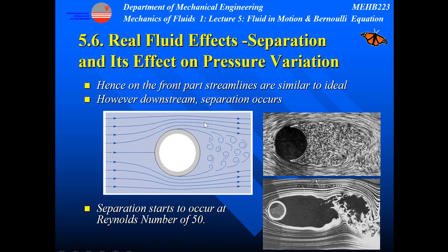You can only see some disturbance here. This disturbance is called wake, W-A-K-E. Separation starts to occur at Reynolds number of 50. The higher the Reynolds number, the more separation or wake will be produced. So see here the wake, there are too many wakes here.